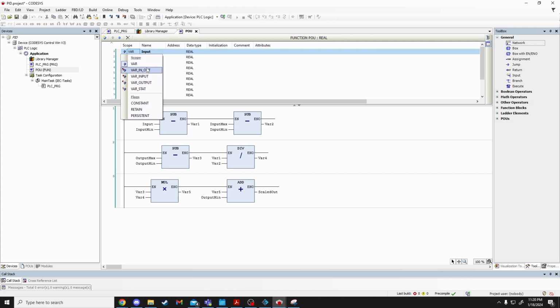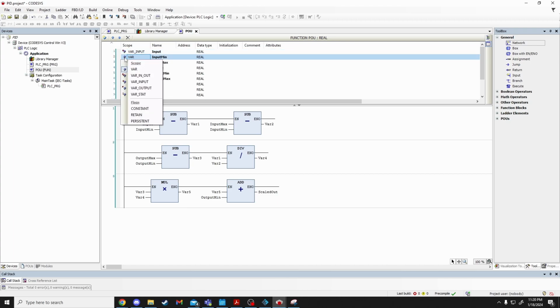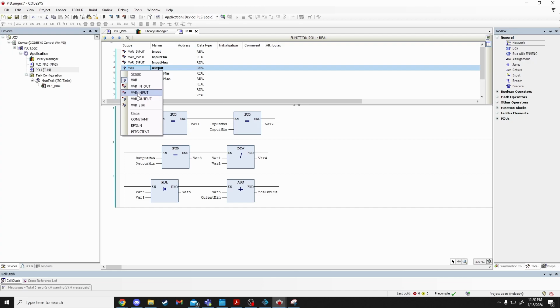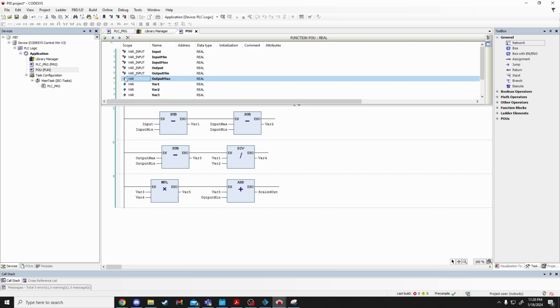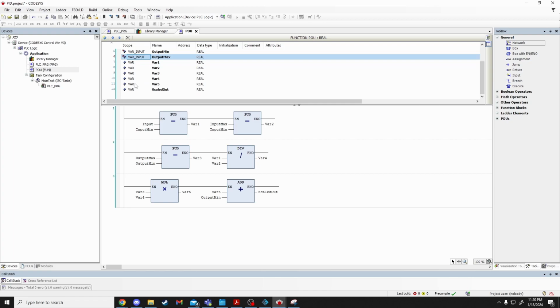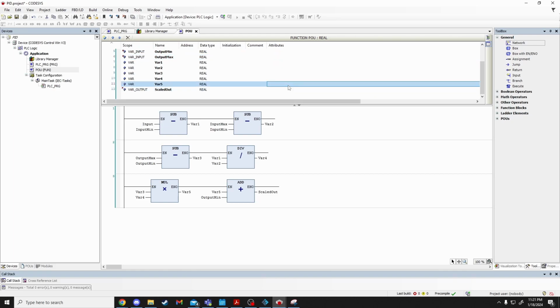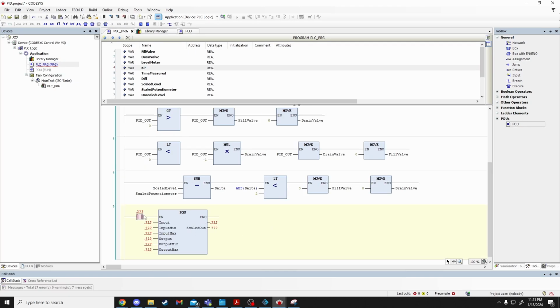We want to put in all of our input variables. So we're going to input what our mins and maxes are. Those are all inputs. We're only going to have one output really. So all of these go to input, input, input, input, input, input. These are hidden. We don't want them showing up on the block. That's all calculated within this function block. And then this is going to be our output here. I'm going to build that function block. There we go. We have some numbers. Beauty.